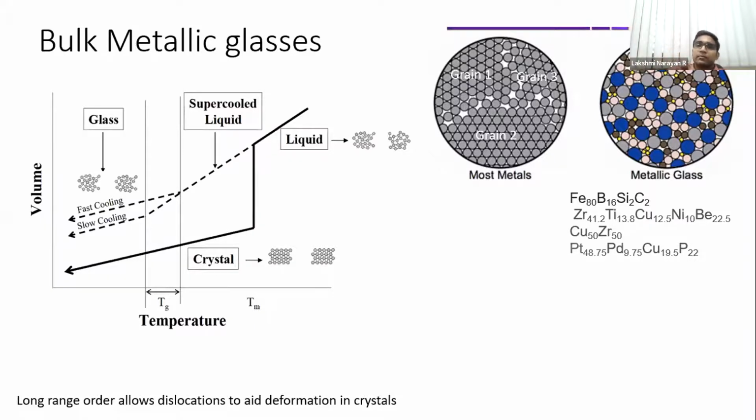If you look at a polycrystalline material, within the grain there is a certain arrangement of atoms. Of course, you call them BCC, FCC, HCP, and several other crystal structures also form. They have some elements of symmetry. In a metallic glass, there is no element of symmetry. They found that there is some kind of short range to medium range order, but beyond that, you can clearly not see anything. In fact, your XRD shows you a very broad hump without any peaks.